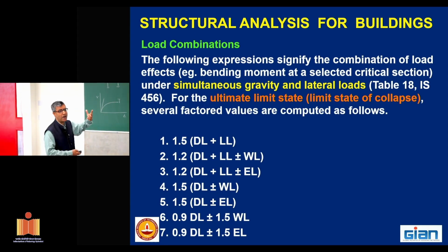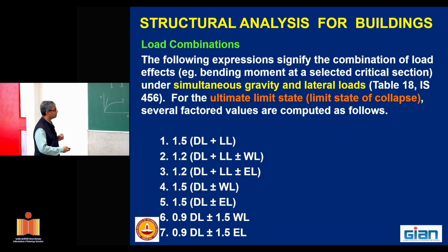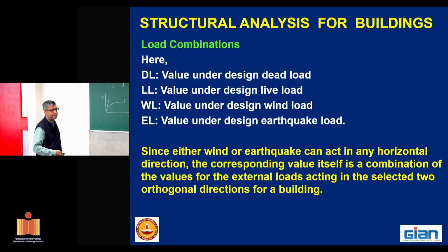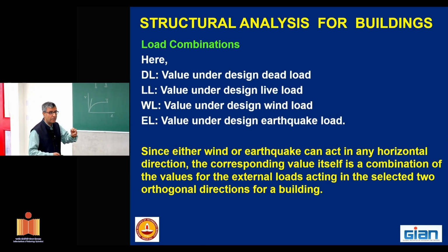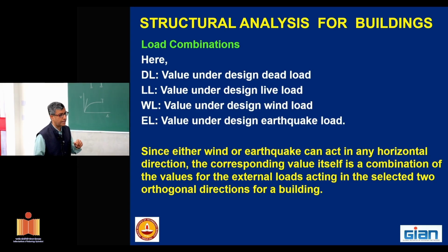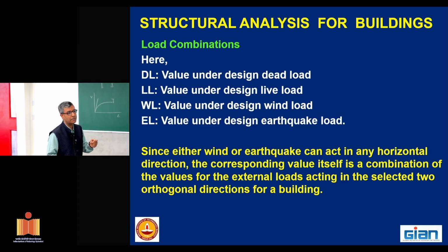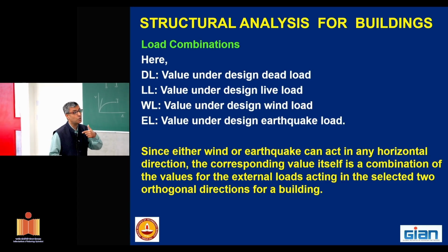Typically you define these load combinations within your computational model as per the code that you are following. So normally for construction projects, the local code. Yes, unless the local code is not defining something, then we go to the international code. Like the other day Satya Silan was saying that in case he's not getting something from here, then he will fall back to the Singapore code, or the Singapore code is more like guidelines.